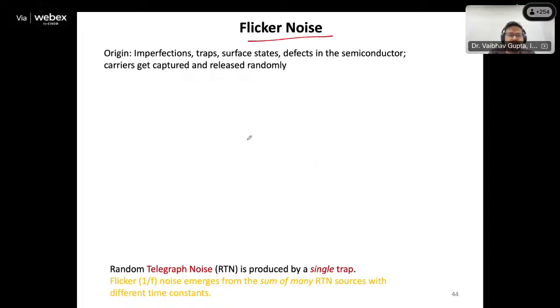Now comes flicker noise. I showed you, we take a glass slide and deposit TiO2 material on top. Suppose you have a material with a conduction band, and this material is imperfect, you did not heat the material and the crystalline phase is not there, so there are a lot of trap states present. If charge is stuck in these trap states and then suddenly drops back, there will be some current contribution.